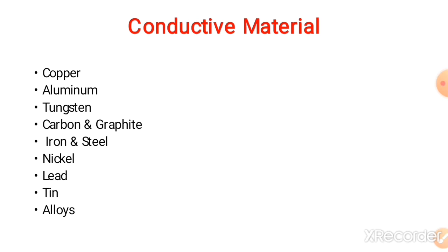Hard drawn copper has high mechanical strength compared with annealed copper conductor, and it is used in low voltage distribution lines. Long span lines require a conductor having high mechanical strength, which is achieved by adding cadmium to copper. The cadmium increases the mechanical strength of the copper without affecting its conductivity. Copper conductor with a steel core is employed for long span transmission lines.